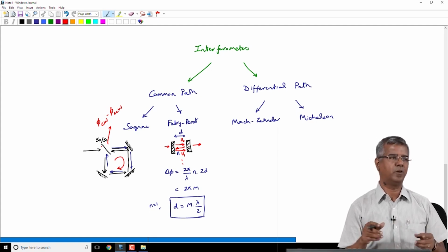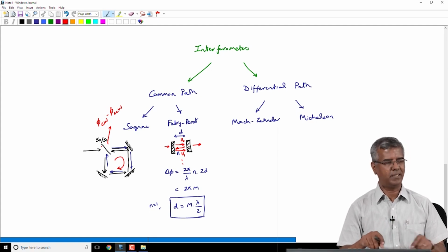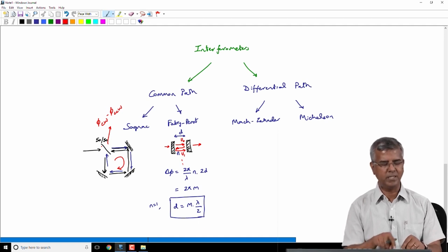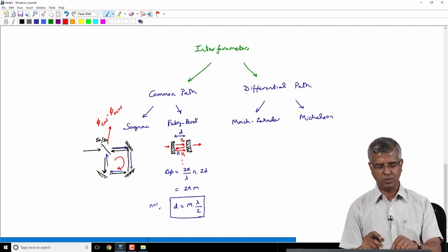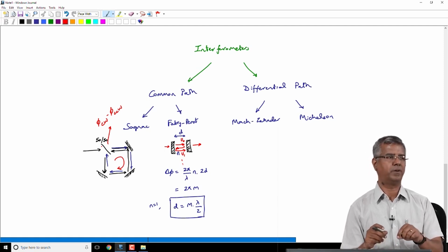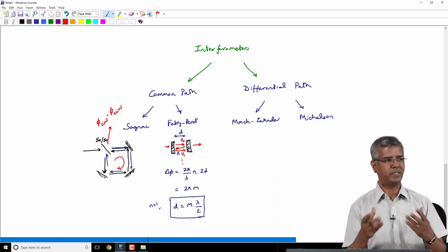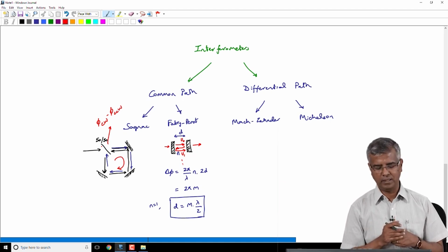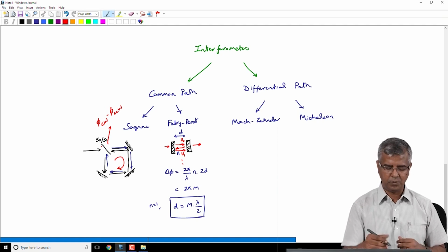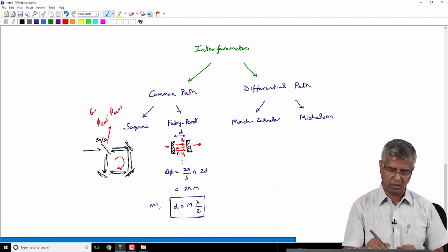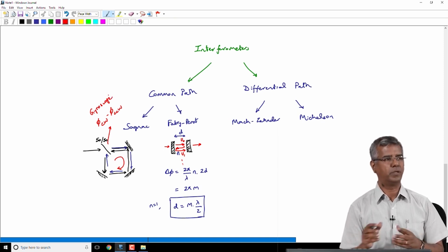Okay. So, it's actually more easily realized in a fiber form, where you take optical fiber and you loop it around, and the 50-50 splitter is actually a fiber optic coupler, and so on. That's the typical realization that you have. This principle is what you call a gyroscope. A gyroscope is something that measures rotation.